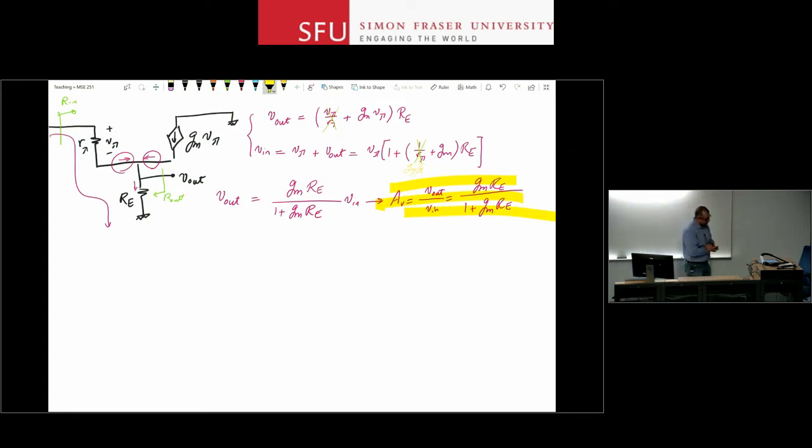Okay, so the reason is that, go back to the definition of amplifier. We said an amplifier increases the signal power, right? And for electrical signals, the power is measured by multiplying the voltage and current of that signal. So it's VI that is the indicator of the signal power. We looked at the voltage gain, but we didn't look at the current gain.